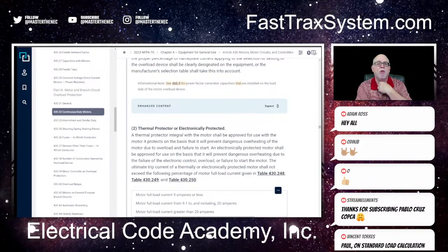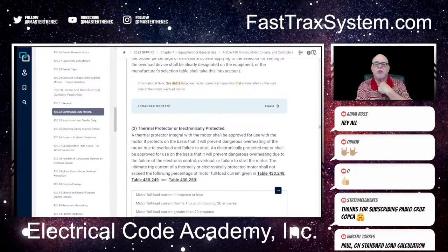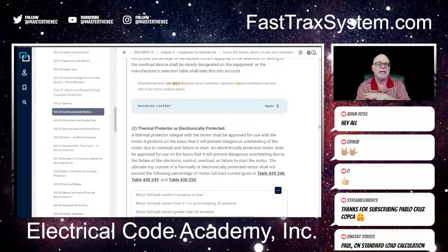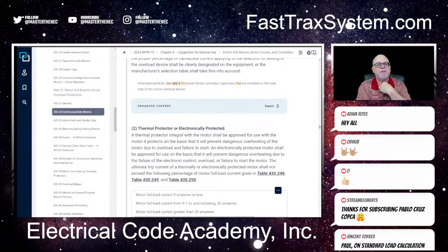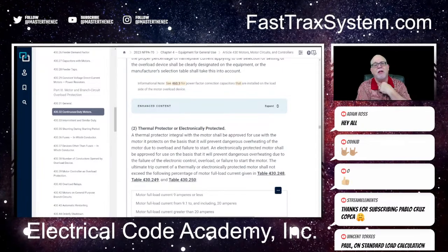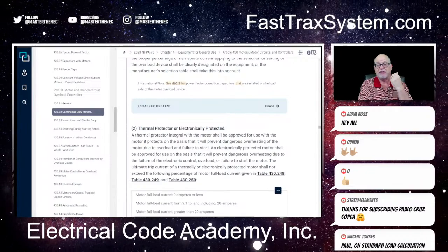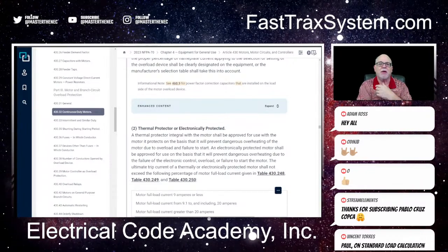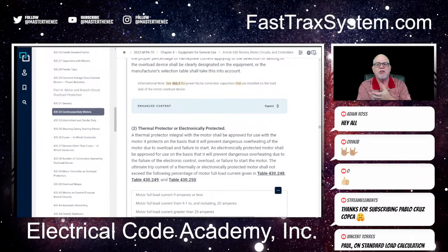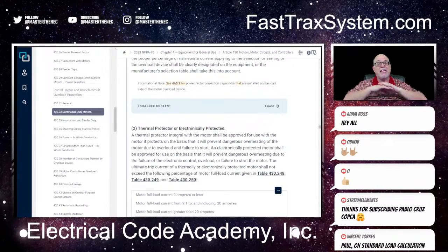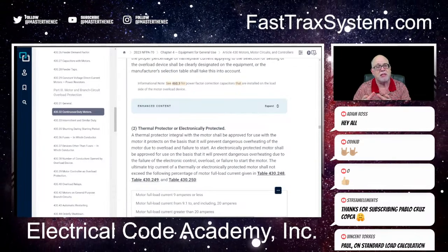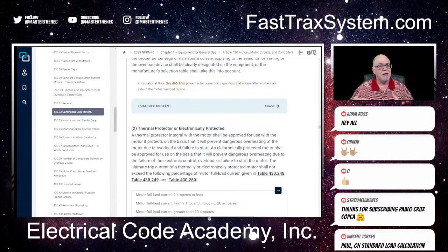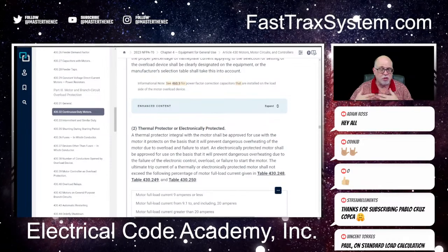So typically I would use, as a default, if you don't know what's going in, the 220.55 Column C, 1 unit default of 8 kW. It's probably what I would do. Now, others might say differently. If it's not there, I don't account for it. But if you're sizing a load and you know it's there, if they didn't run any circuit at all, I wouldn't account for it. But if they ran the circuit and they put the receptacle in, then somebody is going to come in and they're going to plug one in.